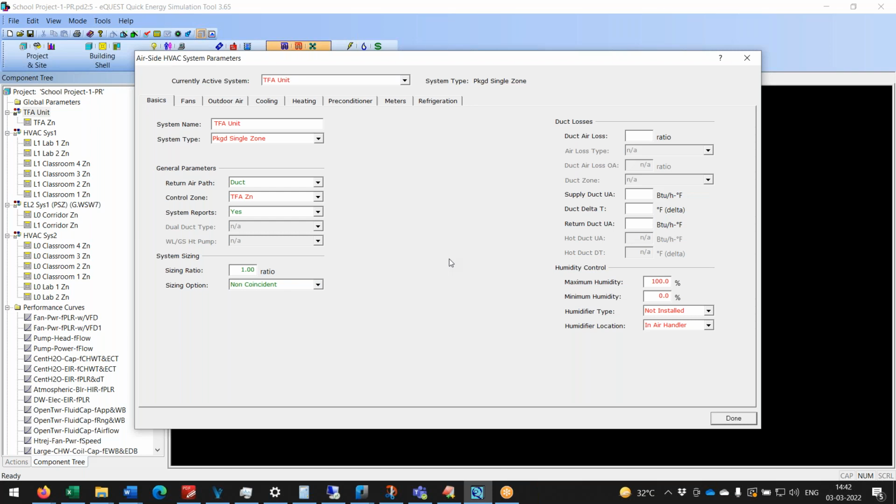Sir, actually, during energy audits, we assess the performance. We get the tonnage either from evaporator side or from condenser side, whichever is possible. While we get the tonnage from condenser side, it should be higher because it is the combination of compressor work and the condenser heat dissipation. So the sum of this tonnage will be equivalent to the heat which is taken by the evaporator in the interior side.